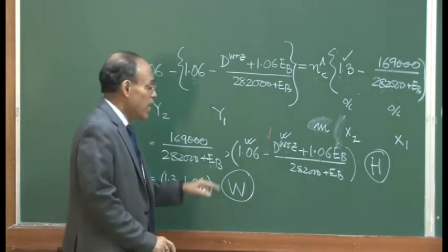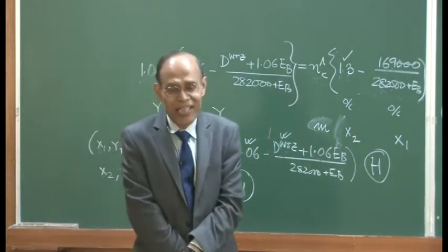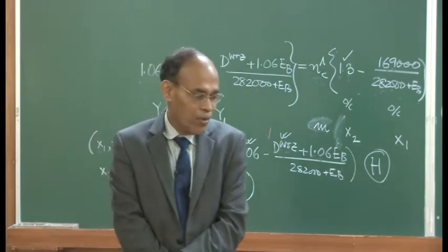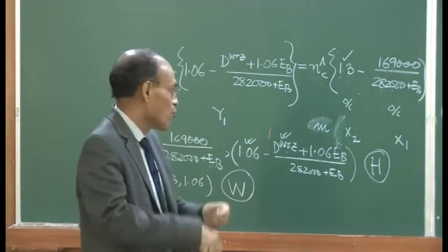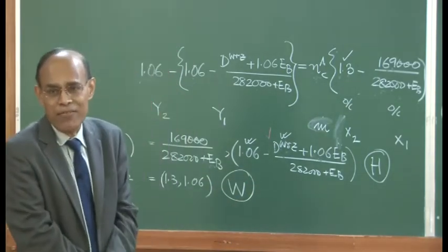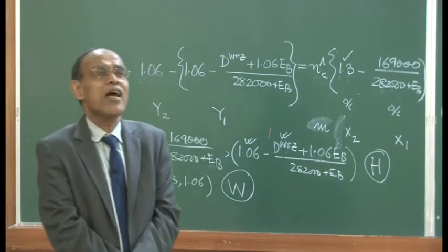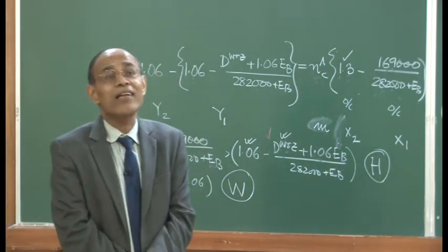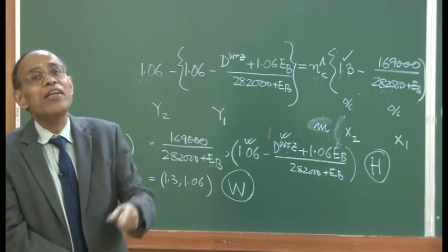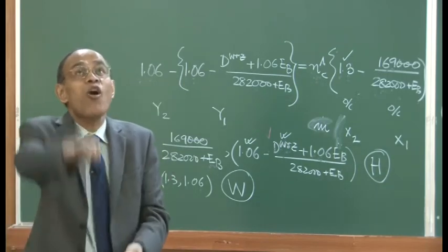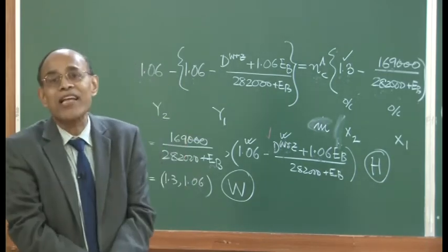So therefore it is desirable to use as high a temperature of the blast as possible. Okay? But of course there are limitations as far as the equipment is concerned. It's a heat exchanger. If you remember, the metallic blast heaters, as I have introduced, used for smaller furnaces, are not as efficient. On the other hand, the stoves that we use really require enormous height, because the residence time of the gas is going to be important.